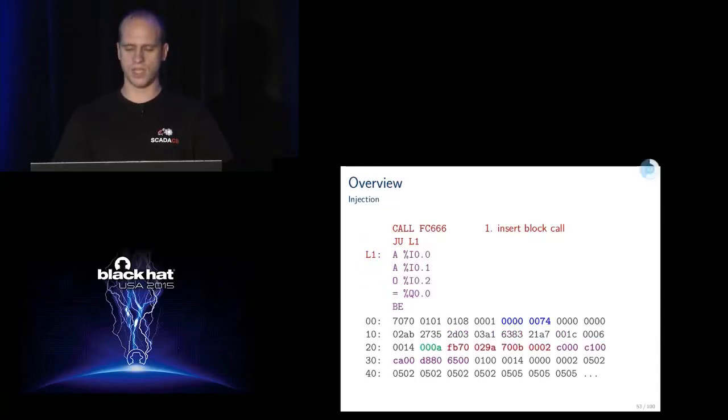So this means we have to add a further 8 bytes. We just need to add 8 bytes for a call that gets executed first, and then the normal control code gets executed. So now we are adding our call, just the bytes. In the second step, we have to increase the local block length. Here you can see we have to add 8 further bytes.